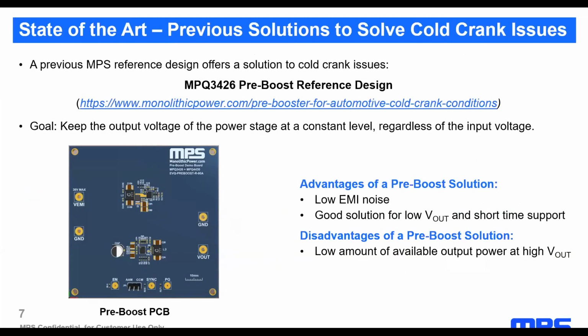In order to solve this issue, MPS has released a reference design aimed to keep the output voltage of the power stage at a constant level, regardless of the input voltage. All the documentation about this design can be found in the link presented here. As a general overview, this reference design consists of adding a boost converter between the input of the system, that is usually the car battery, and a common step-down converter that is seen in lots of automotive designs.